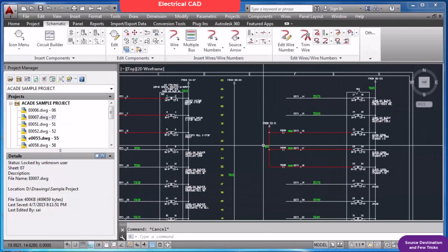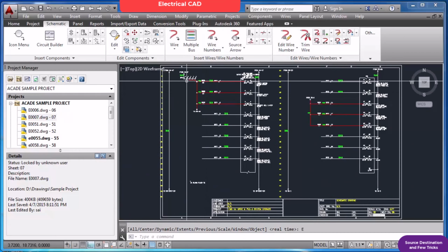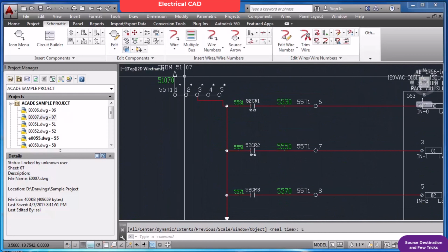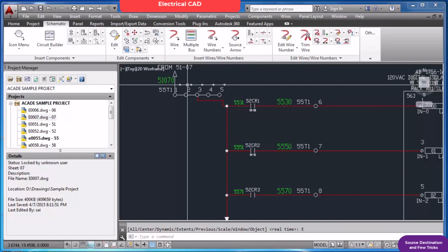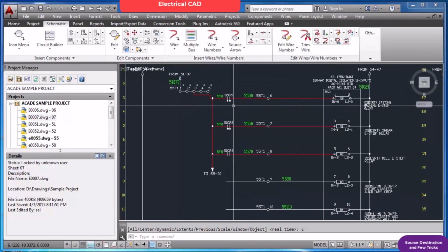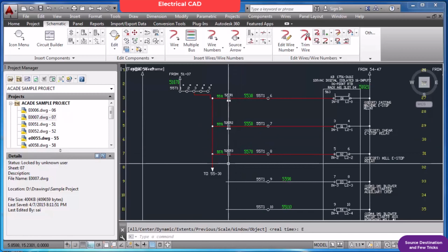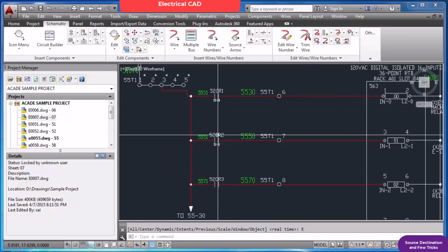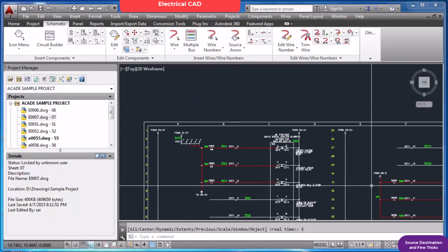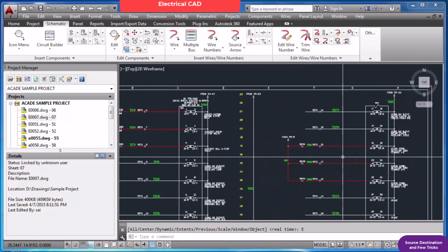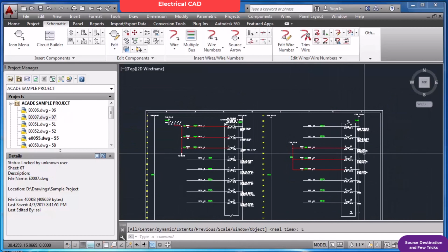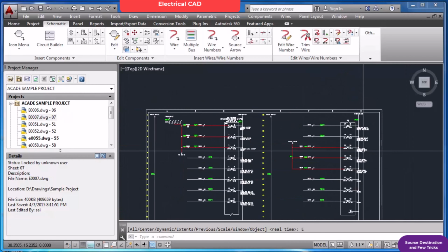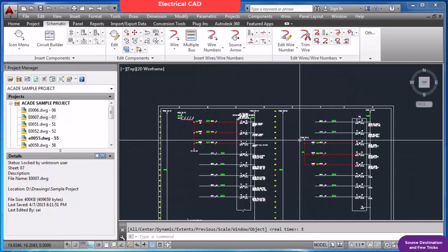Fine. So you can see the 110 volt AC supply phases I am getting from somewhere. So I am looping that supply through these relay contacts from one contact to another, and from here to here. In fact, if these IO list descriptions were here, I would not have used the source or destination arrow.